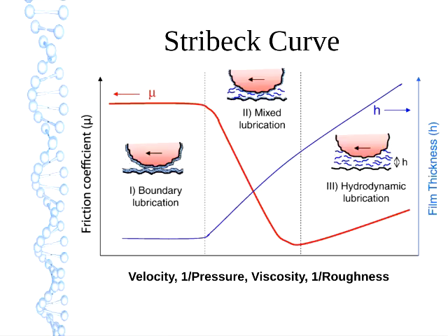And then, during mixed lubrication, as more of the surface becomes separated with lubricant, the friction goes down. And when the surfaces finally come out of contact with each other, the friction will start increasing again, and now you just have the surfaces not touching directly.